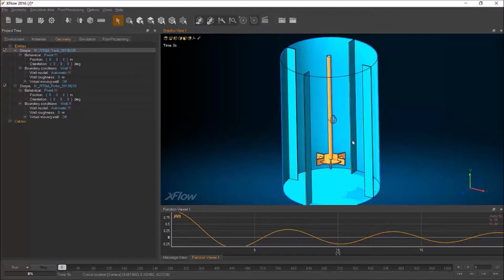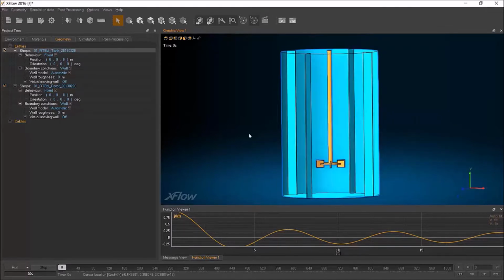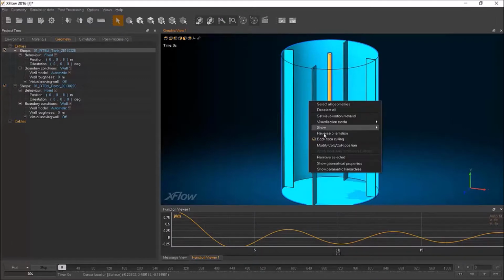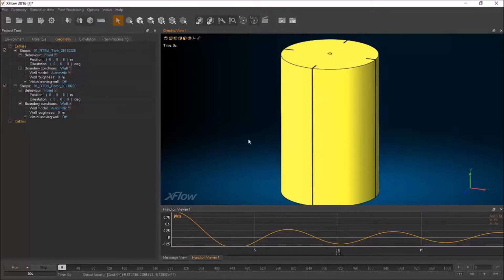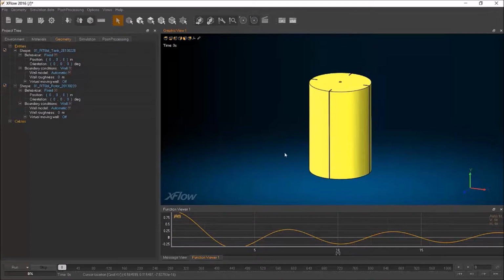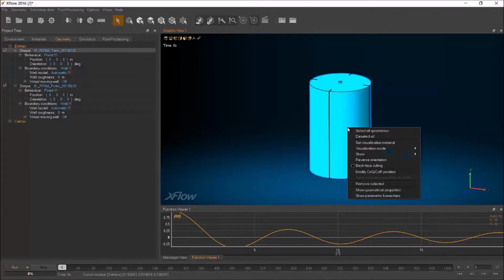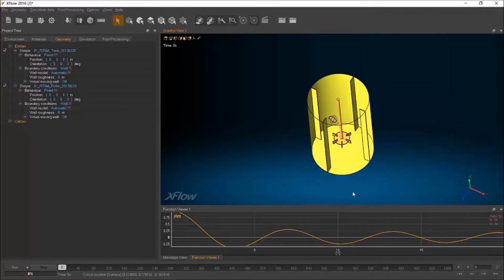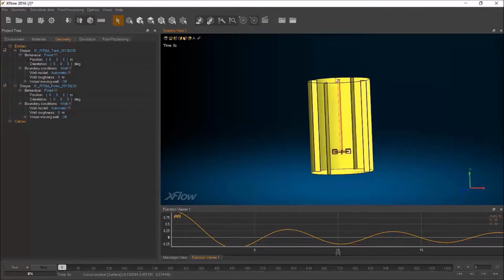You can see, for instance, I can see that tank, I can see inside it, not because there is no surface in front of me, but because we've got something called backface culling. That would be like this. If I disable it, it means I'm seeing my geometry just as is. Now if I enable backface culling, I see through the surfaces that are pointing with normals the other way. So basically I can only see the normals pointing towards me, which means the other one from the other side.